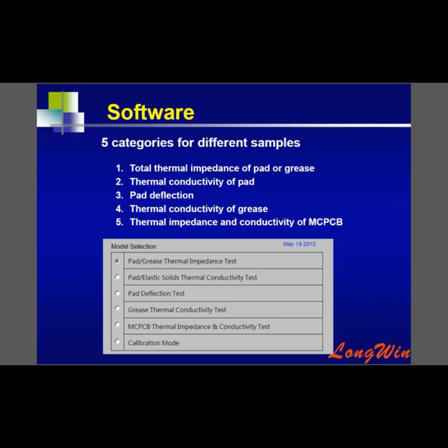The third mode is the measurement of pad deflection. Here we are talking about the soft thermal pad. At different press load, they will have different thickness. So we can find the correlation of thickness and press load, and we calculate its deflection rate.